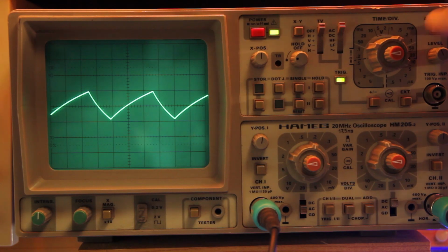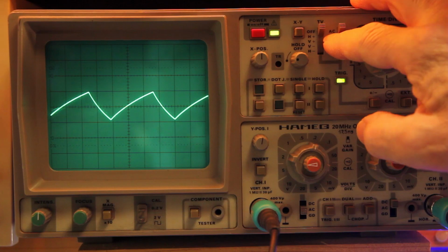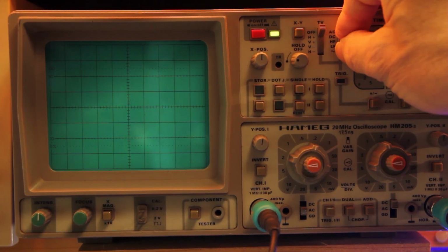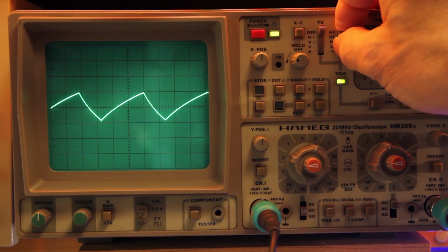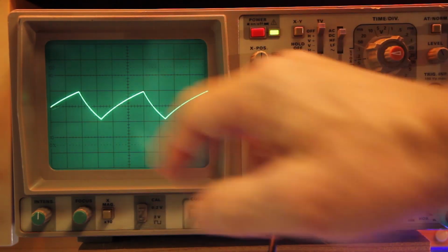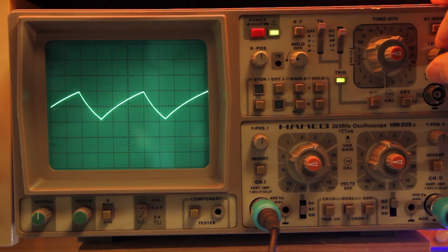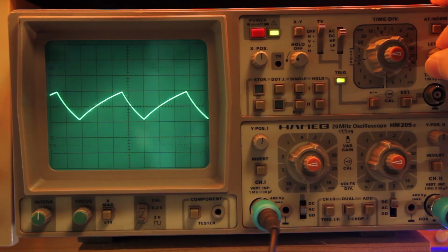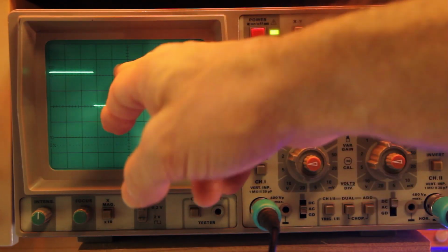We've seen that the trigger offers various facilities to adjust the level of the trigger, but it also has a filter and a coupler which allows us to couple on AC, DC, high frequency or low frequency. So a trick here is that in many cases, for smooth waveforms like this one, it works better using the DC coupling of the signal, because it allows us to adjust the precise point of the waveform we are interested in.